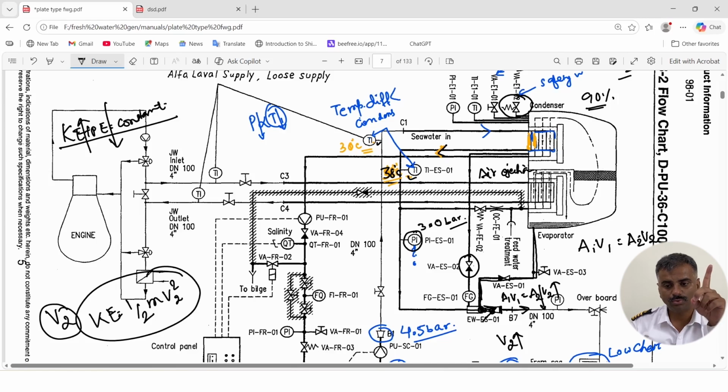And that is the most important concept. If you have steam coming on the top of the condenser, it has to be driven by something which is taking the steam inside the condenser, and this air ejector is playing that important role of creating vacuum inside the condenser plates. Thereby the steam is going inside the condenser plates due to the air ejector.